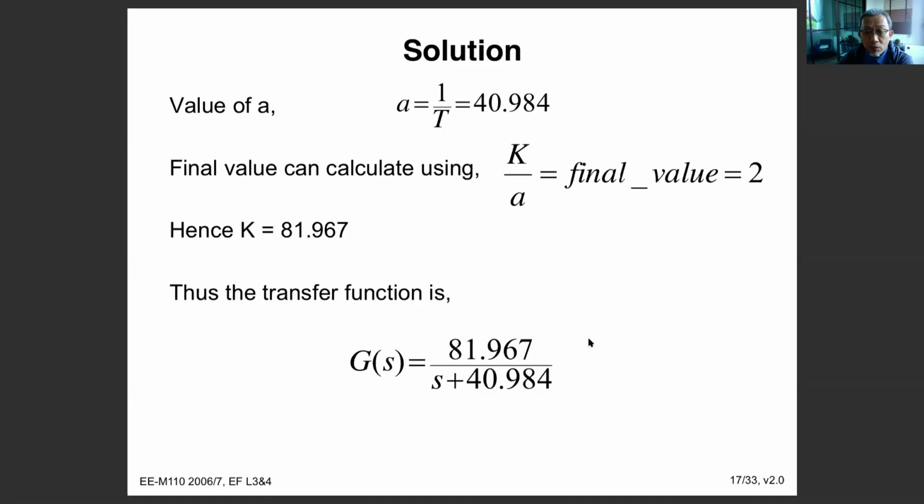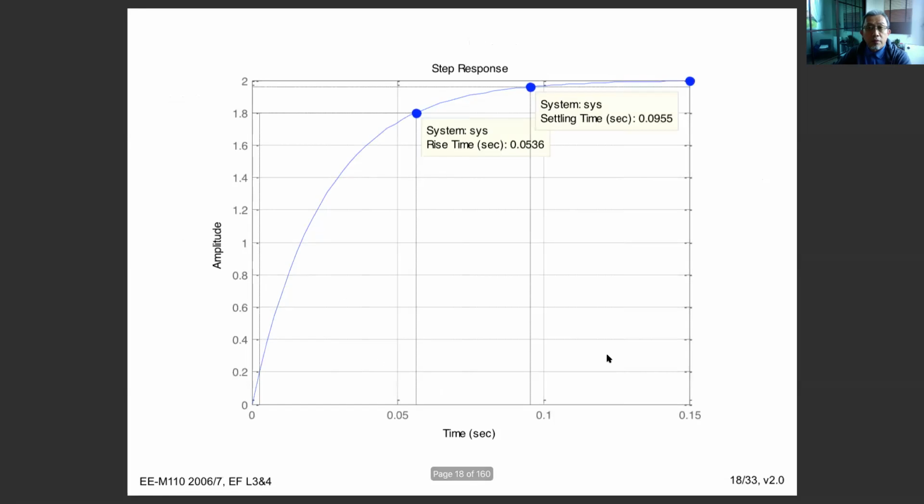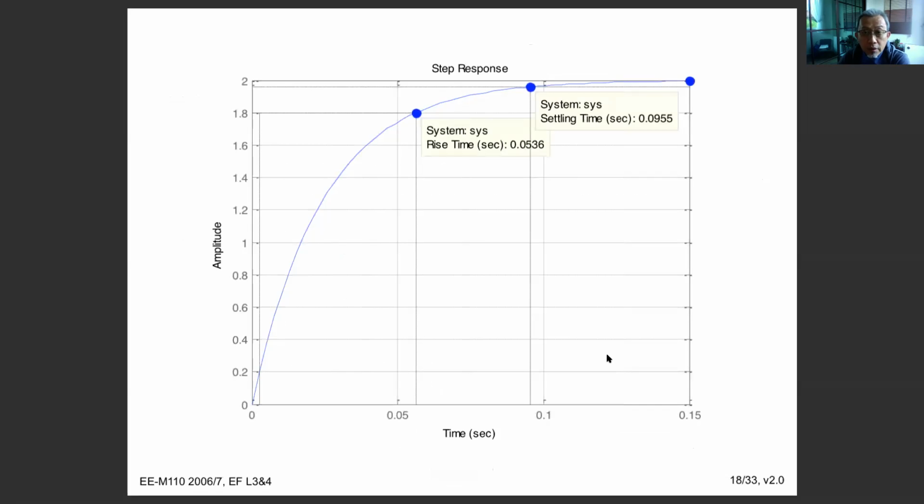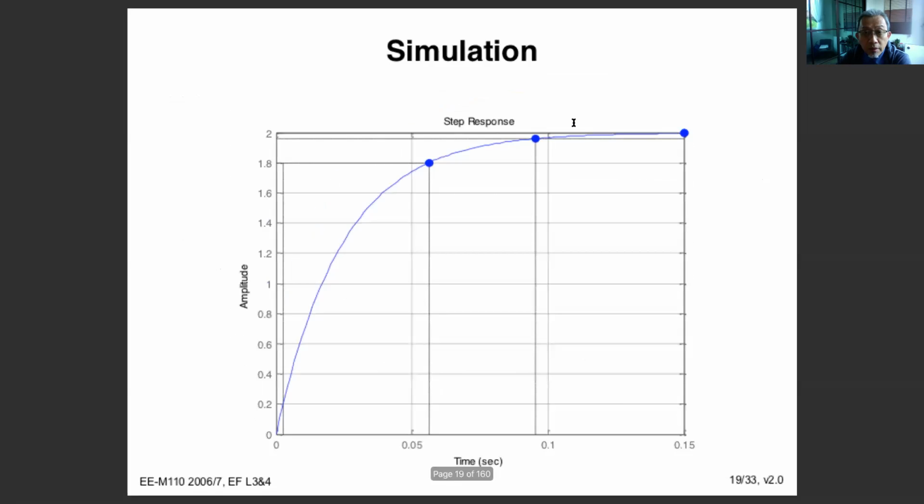I will show you later in the second half of the lecture. So if we go to here, we plot it, so you can get this kind of response. Okay, it is the first order response. Okay, there you go. This is for the rise time. This is for the settling time, and the time constant is somewhere there, which is 1.26. 1.26 is something weird.